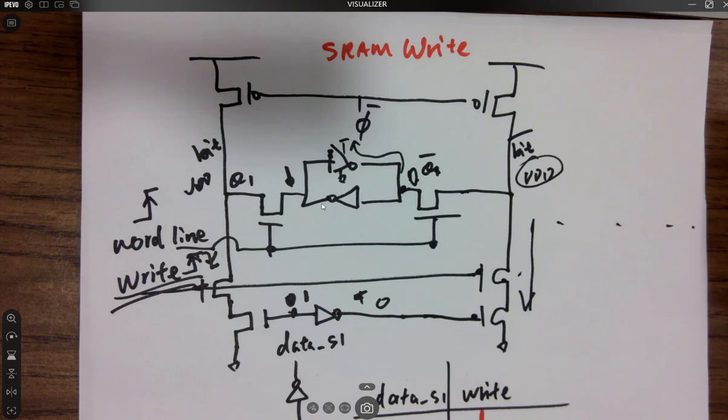I mean, it could be in an interview, could be anywhere else. If you are looking at SRAMs, you will probably see a 6-cell SRAM, so you know what's happening. The 6-cell SRAM is talking about this guy, okay? And it's being optimized because this circuit cannot be synthesized by your Verilog, your digital description language. If you haven't taken that, it will be covered in 433 in the spring.